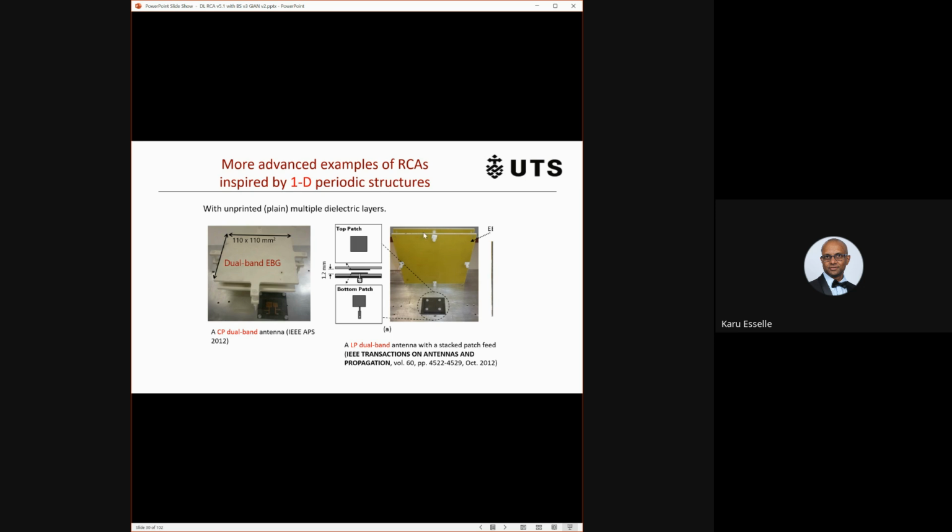So in this one, again, we designed the cavity to resonate in 2 bands. This is opened up, like when you operate, we close it down. So design the resonant cavity to operate in 2 bands, and then we need a dual band antenna to excite it. One way to do it is using a stacked patch microstrip antenna. That's a normal microstrip. This is the lower patch, and this is the upper patch.